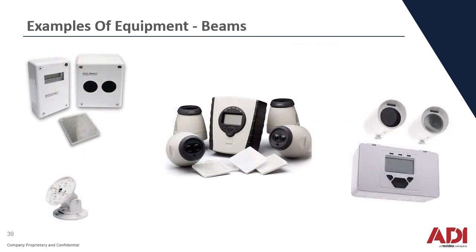Next, we have some examples of beam detection. There are two types of beam detection, end-to-end and reflective. They transmit a small beam of light from one end to the other. If smoke passes the beam light, this is seen as a fire condition. Common units are the Fire Beam company, which is reflective only, FireRay, which have both reflective and end-to-end solutions, and Xtralis, again an end-to-end system. Remember, these need interfacing onto the main control system and are not standalone.